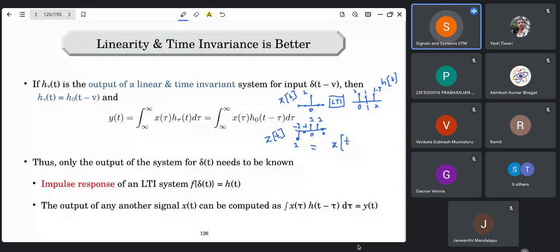So there is an impulse at -2 first. So I have to shift it to the left, and that is the negative direction. So X of T plus 2 captures this sample. And plus X of T captures this sample. And the final sample is now captured by another term, which is X of T minus 2.